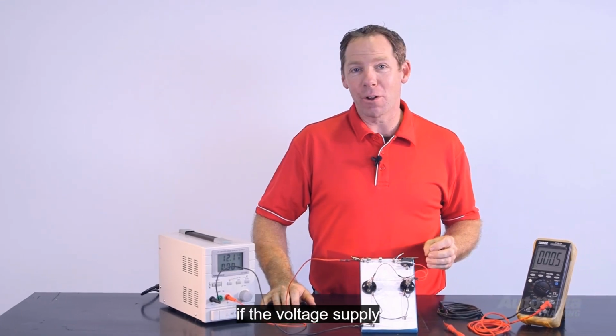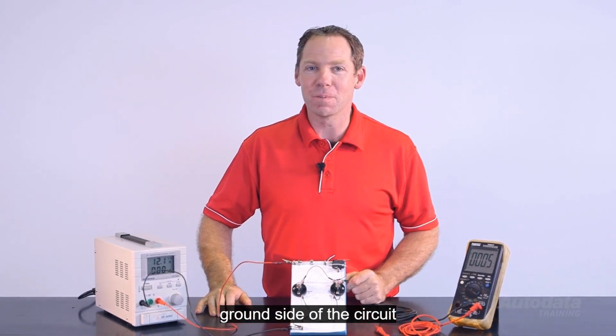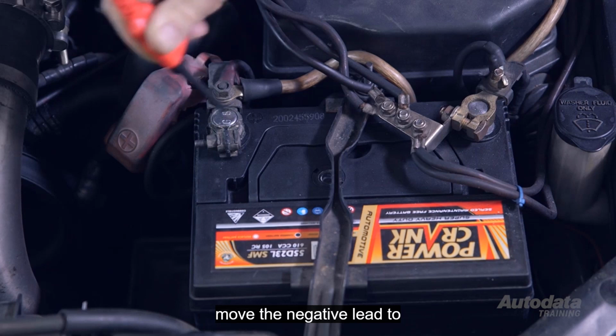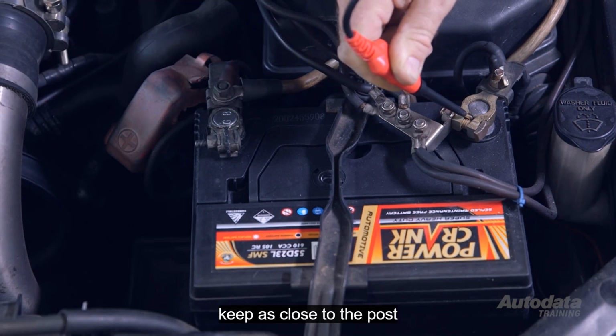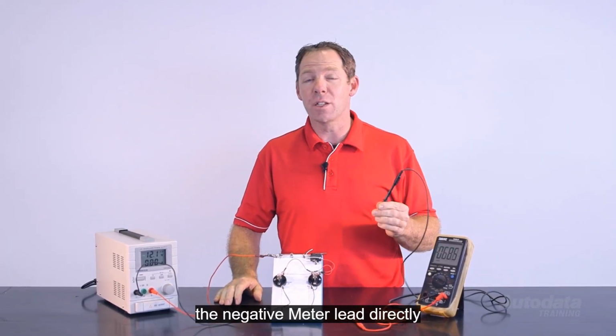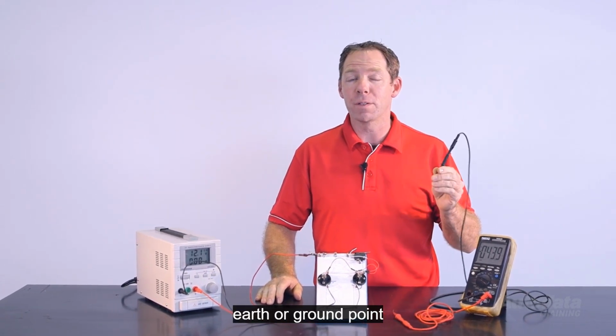If the voltage supply has no fault, then it's time to test the ground side of the circuit. Again, if performing this test on a vehicle, move the negative lead to the negative battery terminal. Again, keep as close to the post as you can. Don't place the negative meter lead directly to the chassis earth or ground point.